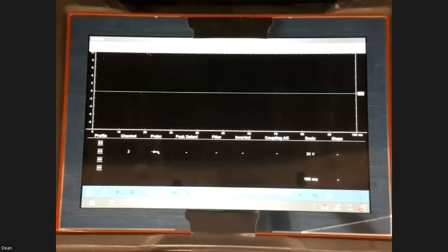So you hook it up, you take your digital voltmeter, and you check your battery voltage, and it's at 12.59, which is okay. It's at 90% battery life. Is that good? Well, most people say it is. How do you test it now? Anything in an electrical circuit, you have to check loaded. You cannot check it just stationary. To test the battery correctly, you have to let the battery do what?